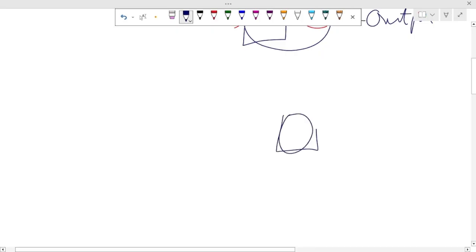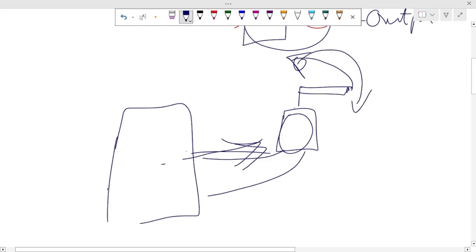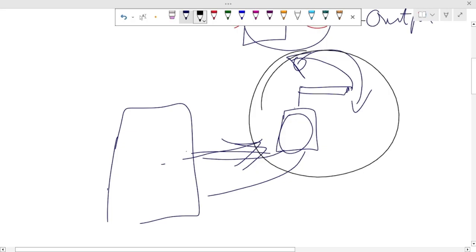Okay, this is not a very good drawing, but it has something like this here. So base, and of course connected to the ESP32. Based on the inputs, based on the signal sent, this servo motor will rotate from 0 degrees to 90 degrees. And based on inputs from the ESP, it will rotate from that 90 degrees back to 0 degrees. So this servo motor is connected to what? The hinge of the door.